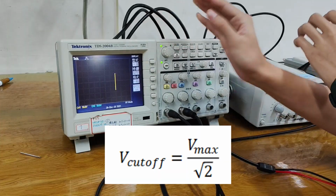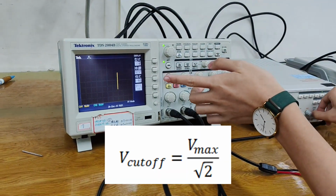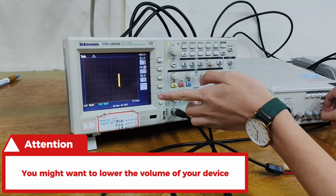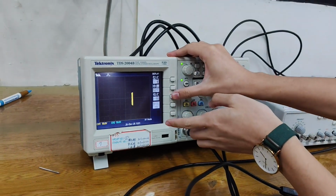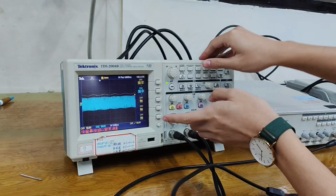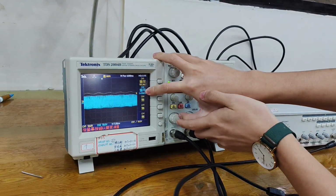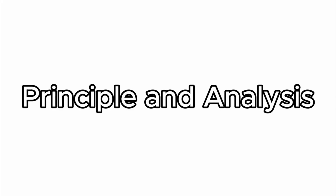Then we multiply by 1 over square root of 2, and it's about 2.1. We shift it, maybe here, change it back to YT mode and use the measure function to see it. So this frequency is about the cutoff frequency that we want to find.